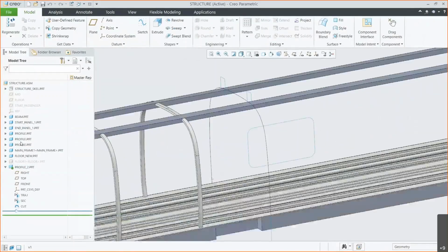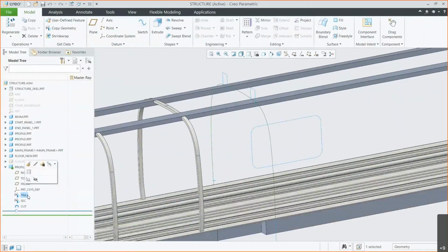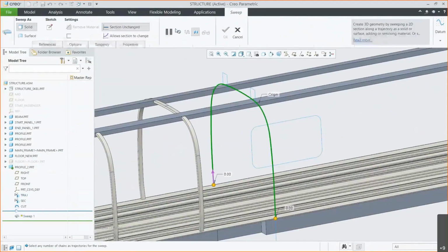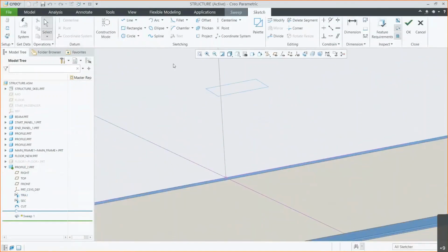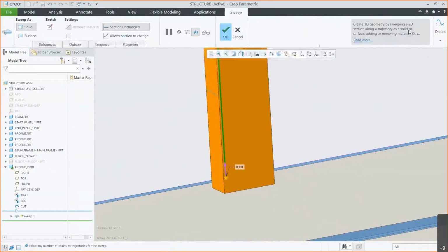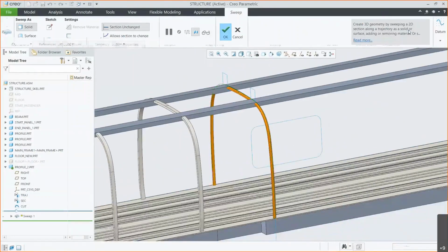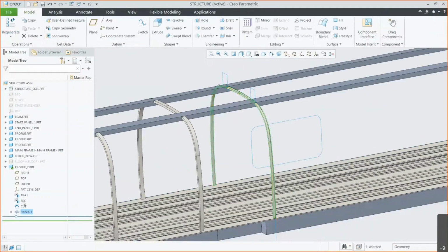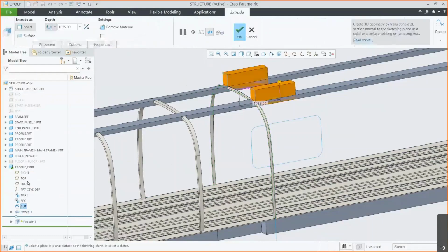So for example, here, if you have this arch and you have the window and you need to start designing for the structure, all you have to do is use typical processes. So you can project this loop around, and you can actually use the particular curve. So you can either project the curve and reference it, or you can use it for your regular Creo activity as if it was the sketch that you made. So past that point, right, this is just regular Creo work.